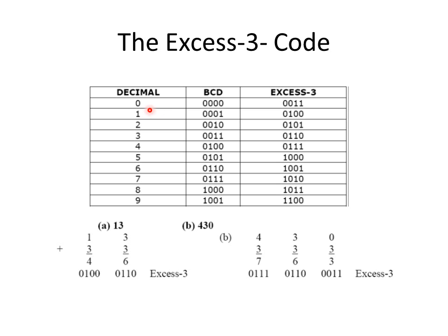For example, decimal 0 is 0000 in BCD, but when 3 is added, it becomes 0011. Similarly, for other decimal numbers, 3 is added to the BCD code, and in the case of 9, if 3 is added, then it is 12. Therefore, in XS3 code, the binary symbols start from 0011 and the last binary code is 1100.